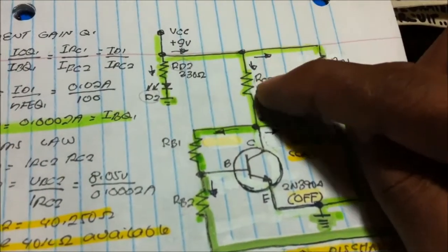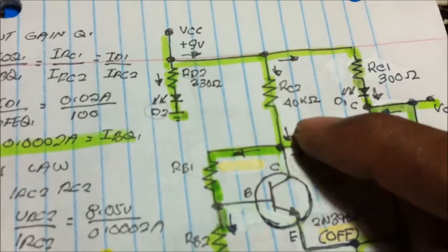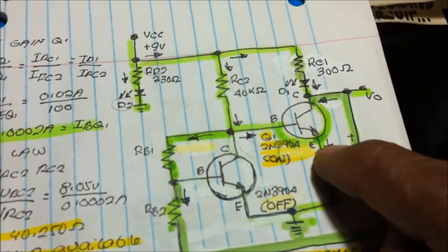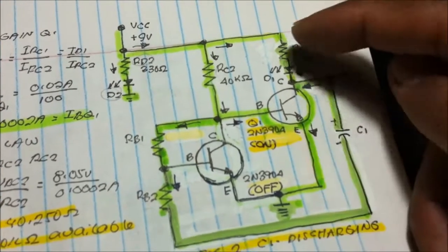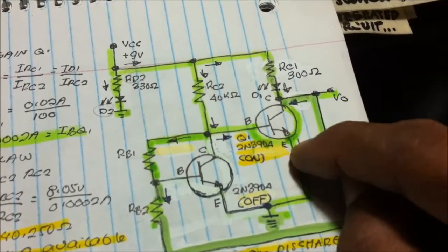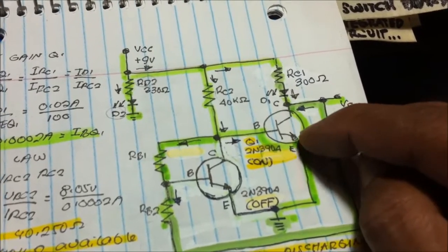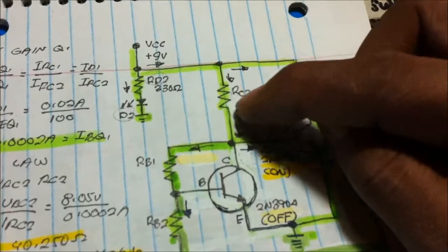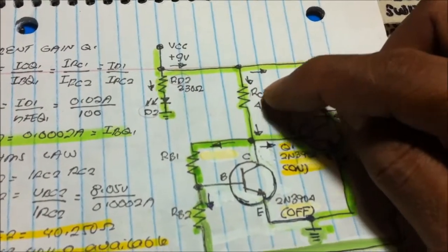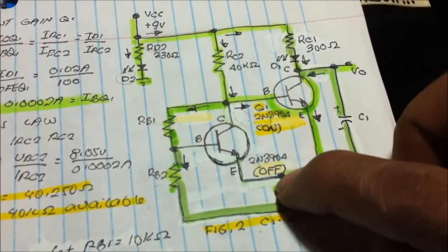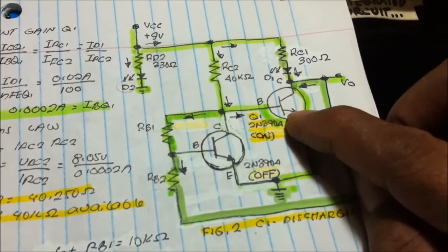But here current flows into the RC2 and into the base emitter of the transistor, making this forward bias. Because of that, current flows into the output side of the transistor 1, making this LED turn on, close to the ground. So we can now use this equation. KVL at VCC, RC2 to QBE. We're going to compute for the value of RC2. VCC, voltage drop at RC2, voltage drop at base emitter and to the ground. This is now forward bias.